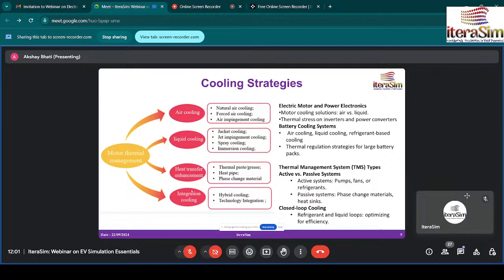And what is the mechanism? As the fine droplets evaporate, they absorb a significant amount of heat from the surface, lowering its temperature. And we can also get the advantage of the latent heat of evaporation. So in a much smaller area, we can remove more heat. Another one is uniform cooling. It will be sprayed onto a uniform area of the winding.